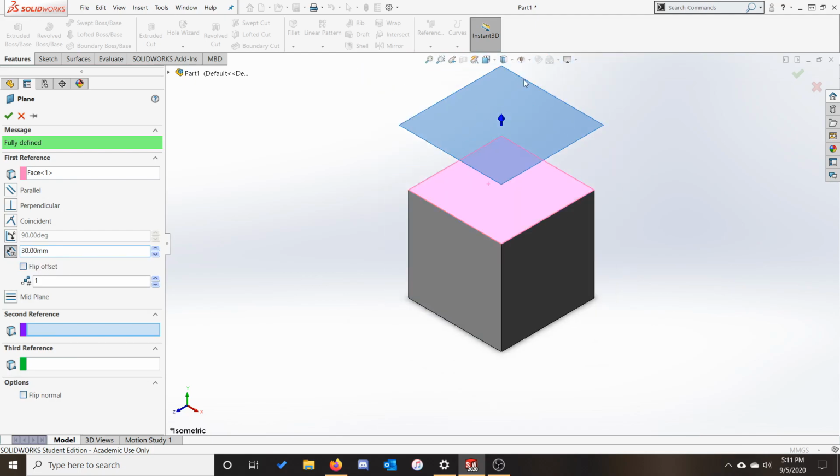This creates a plane that is parallel to one of our pre-existing surfaces, which often is not entirely necessary. With extrude, we can use the offset starting condition to get a distance between the sketch plane and where the feature begins.